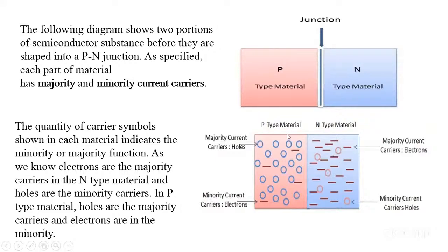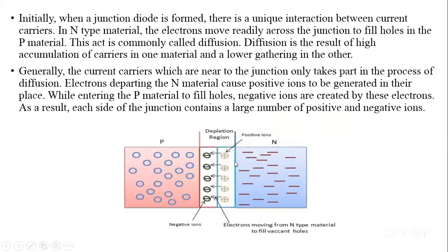At the junction, you see electrons crossing to fill holes in the P-type. While they are doing that, they are forming a depletion region, an immobile region. This depletion region will keep expanding until it gets to a level where more electrons from the N-type cannot cross to the P-type to recombine again.